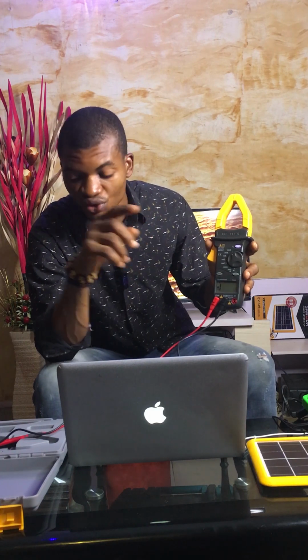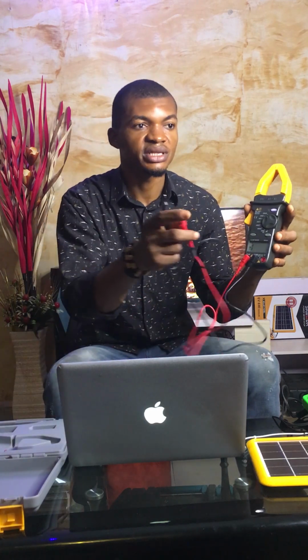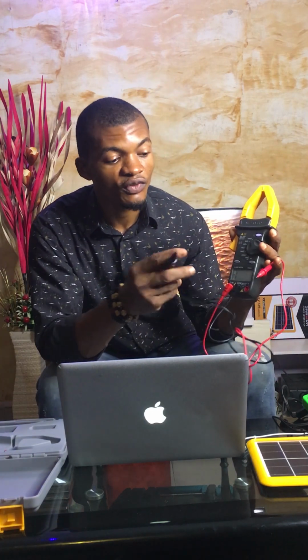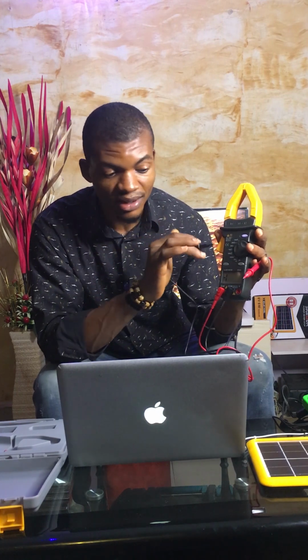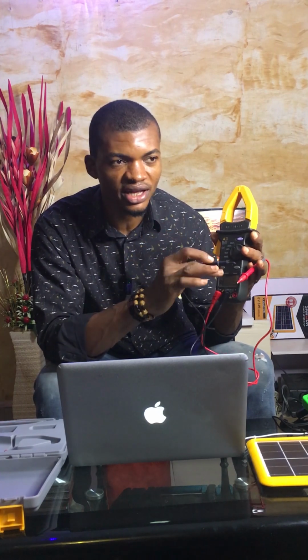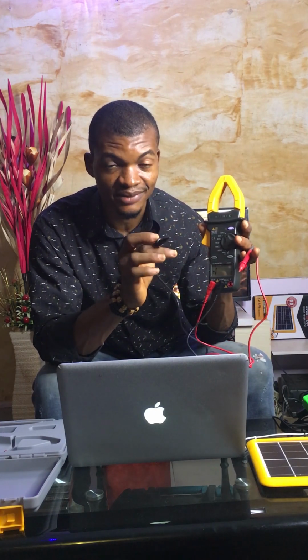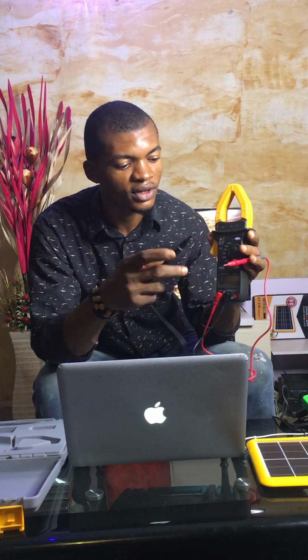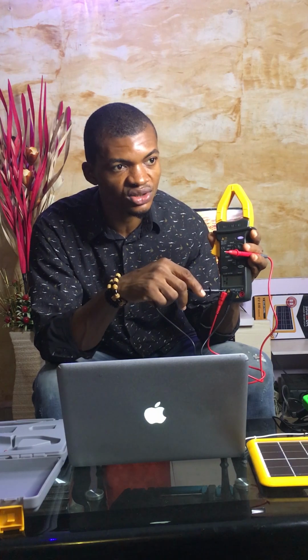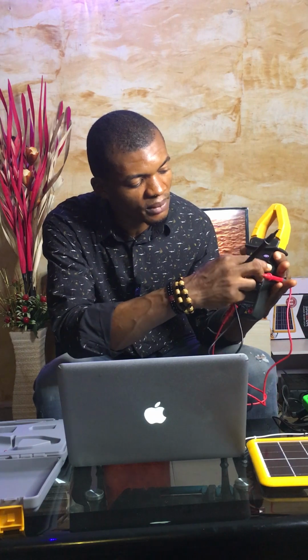Then the frequency also. Then here, I'm going to measure the continuity of this particular cable. If I get it right, there will be a sound that the buzzer will give me. That sound indicates that the cable is true. There's no blockage in between, no cut along the line. Everything is intact. Therefore, whatever flows from here will be gotten here too. So I'm going to select it to the ohm meter side.